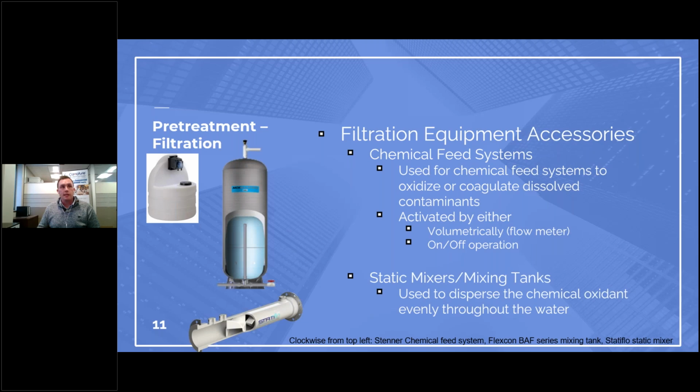Along with those chemical feed systems, you may or may not need this, but a lot of times we do recommend some sort of mixer or contact tank. What it allows you to do is make sure that the chemical solution that you're adding, oxidants, coagulant, whatever, is thoroughly mixed and then evenly dispersed throughout your water. So that way you get the best reaction available to you.